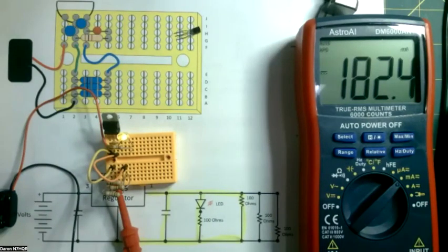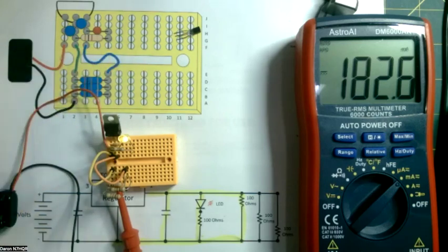So if the tab is not grounded, if it's the opposite, as you say, if you connect to a heatsink, does it have to be isolated from ground of the chassis? Yes, absolutely. That's why I was saying that has stung me before, because it's a 317, I think, an adjustable voltage regulator in that same format, a 3-tab regulator like that, and you just put a resistor in there to determine what output voltage you want. The tab on that is positive, I believe. So you don't want to mount that to your ground bus. You don't want to have a heat sink on there that touches the case or anything else. You want to be aware of that. Or you can put an insulator in there. Lose a little bit of efficiency, but yeah.